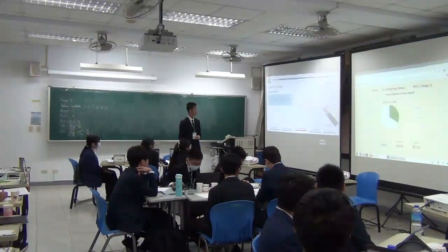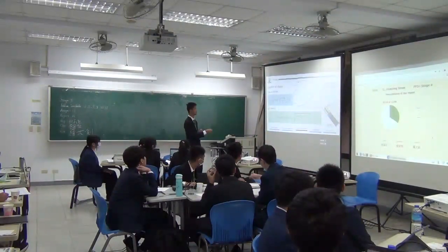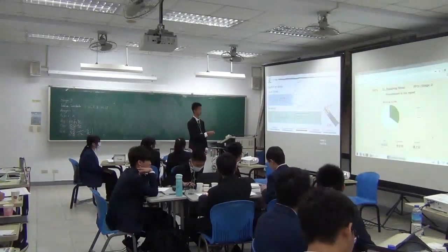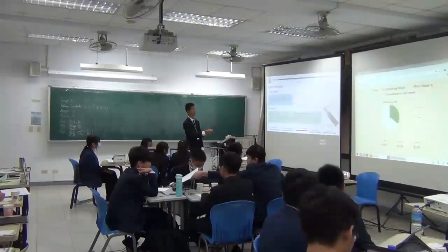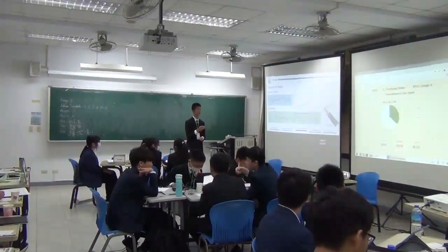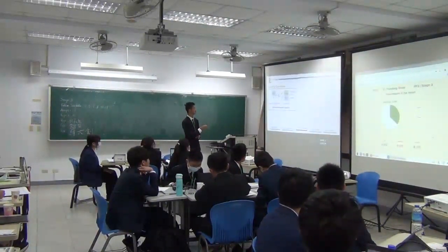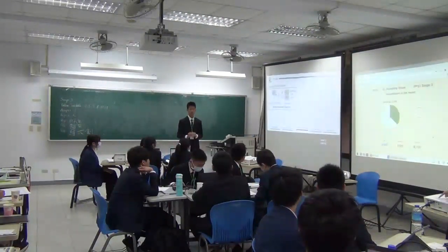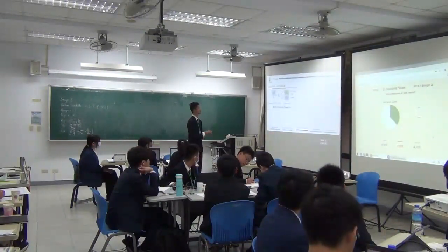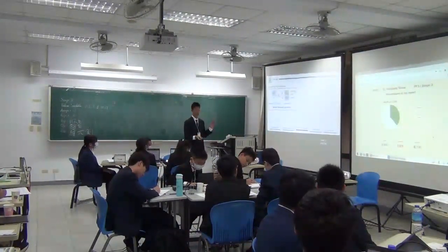Given tau, we can differentiate to get the radial velocity and the exit velocity, which is simply v of tau, given by this equation. Here you can see that the height of the water segment, h of t, as a function of time, will increase, and the increase is getting higher and higher, so acceleration is increasing with time. So here, because we are dealing with a fluid and not a point mass, we have to correct it using some other factors. So for example, the viscosity is given by this equation. Given the average flow speed and the diameter of the straw, we can calculate the pressure difference.